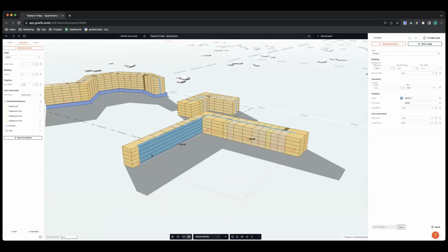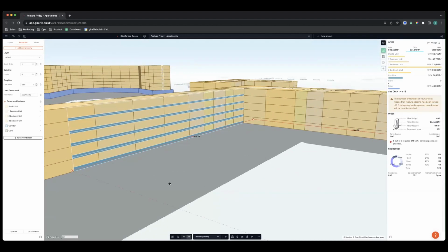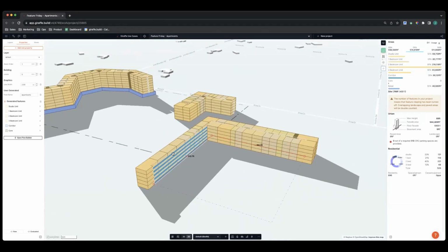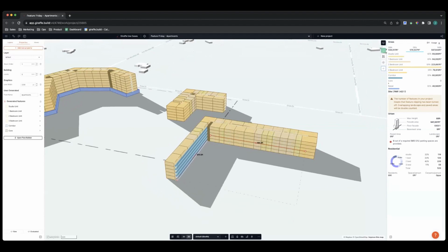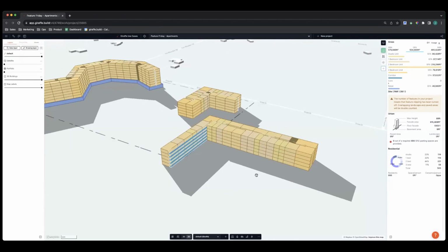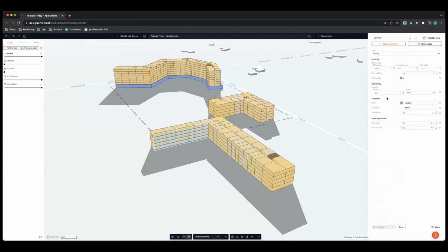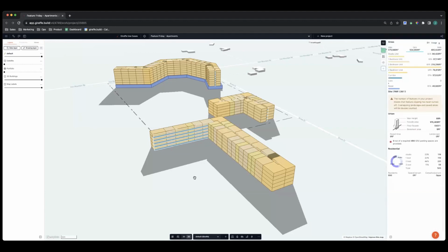But in this case, I want to get rid of the facades because I want to do an exposed hallway. So we can say no facades, and that's a property in Giraffe that it understands. And when I hit that, you'll notice here that now we have this beautiful open hallway that's looking out over our courtyard. Very classic for commodity condos or apartments to have an external hallway like that. So pretty cool. Just to recap that, we went to corridor and we changed that to have no facades. I added this property called no facades. So there's a bunch of different ways you can use that.